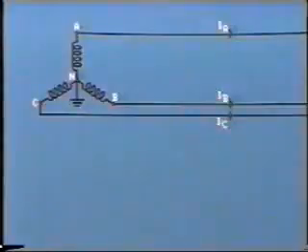To do this, we'll need to study the associated phasor diagrams. Here we see the simple three-phase system functioning under normal, balanced conditions. The circuit has been simplified by removing transformers and breakers. The neutral is solidly grounded in order to anchor the system voltage.